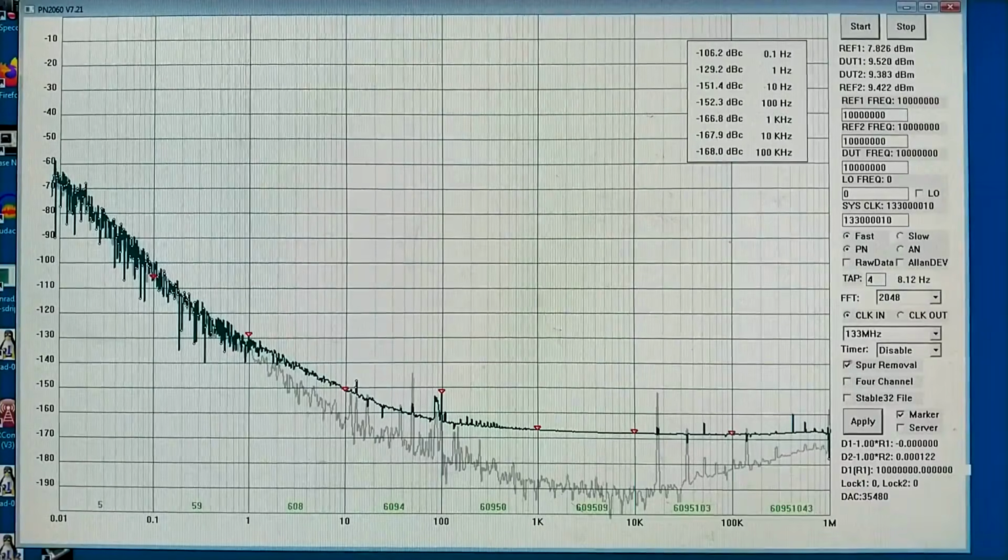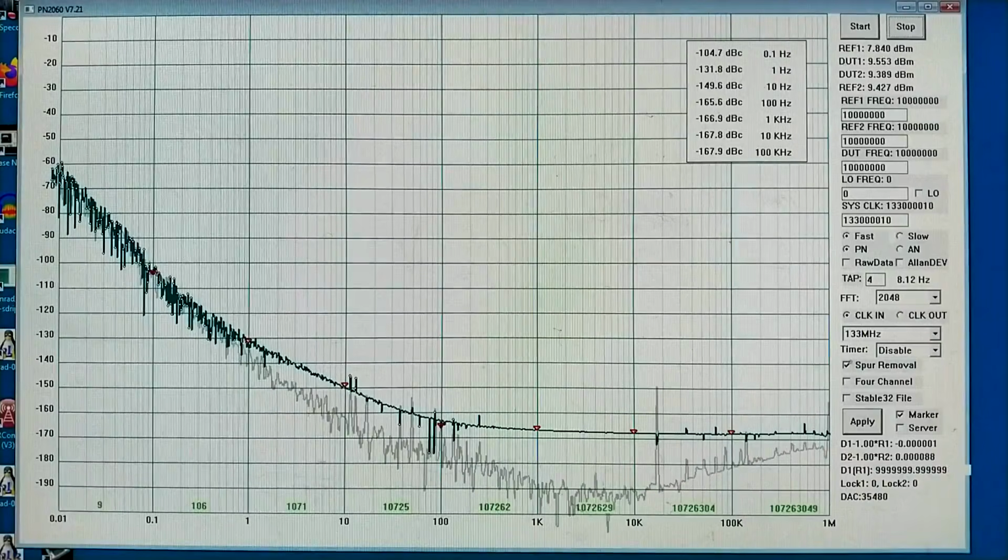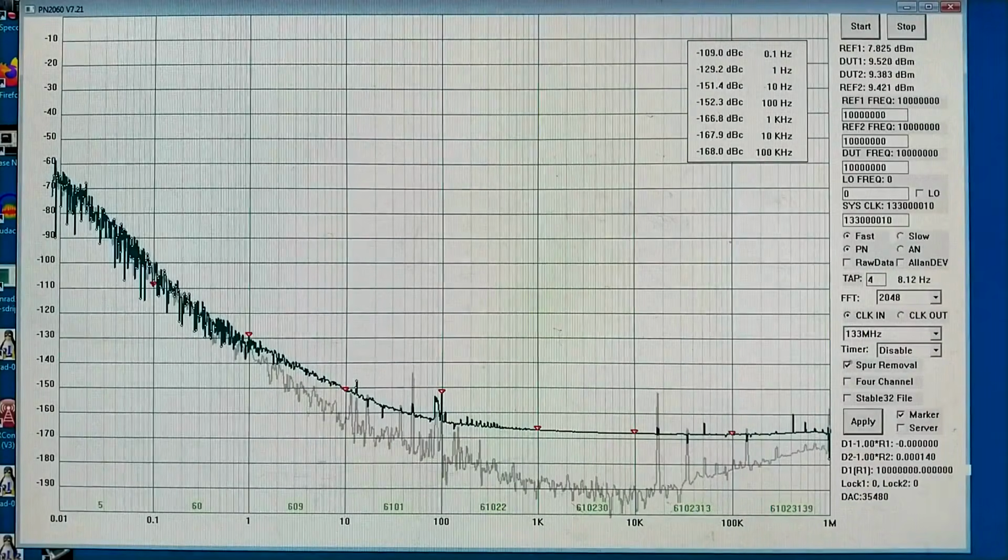I have reduced the supply voltage from 16 to 10 volts. That has reduced the power from 230 milliwatts to 103 milliwatts for the source follower. 20 milliamps, 11.5 volts, and now 15.6 milliamps and 6.6 volts for the transistor. And the result here is a little bit better. This was at the full power, and here is what I have now at reduced power.